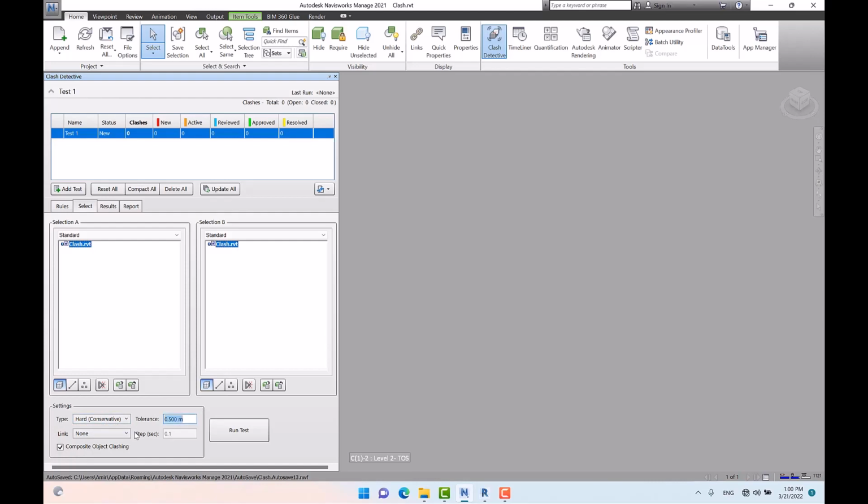First of all, what is the tolerance here? We talked about it in the duplication, that if you specify 0, it means that the two items should be exactly overlapping each other, and then in clearance I told you that the value you specify in tolerance is the minimum required offset. So if the distance is less than the specified value, then it will be reported as a clash. And here if I specify 0.05, it is the minimum value for which two objects overlap each other. For example, we got two objects that are exactly parallel and overlap each other slightly at their ends. Here if I specify 5 centimeters, the 5 centimeters overlapping is not going to be reported, since we are not going to face problems.